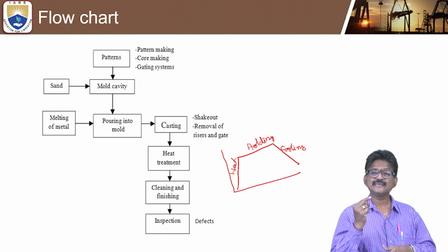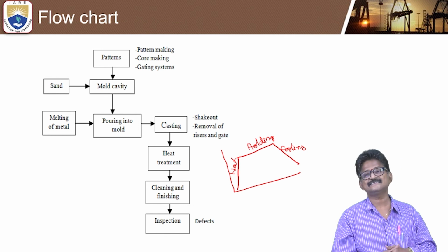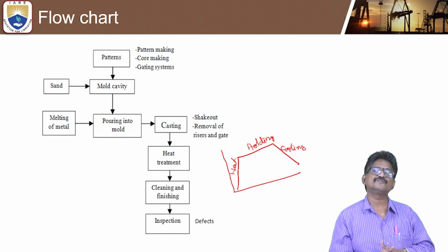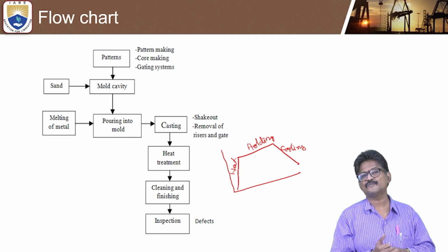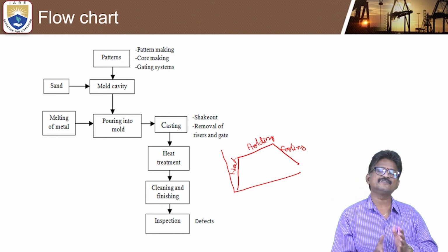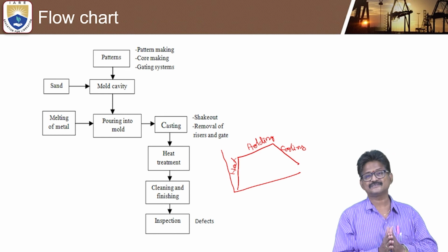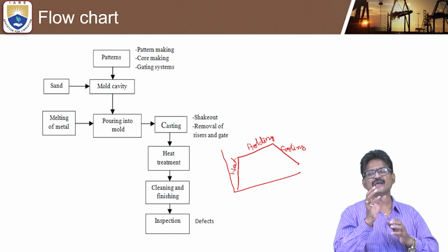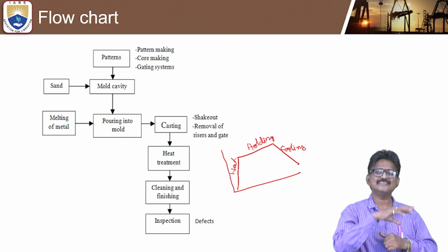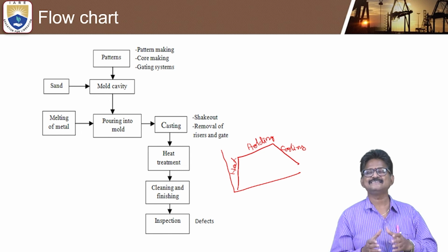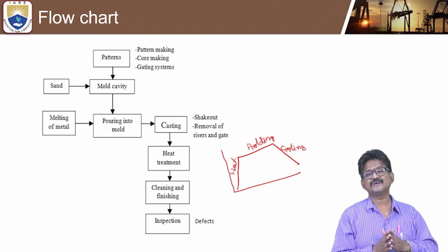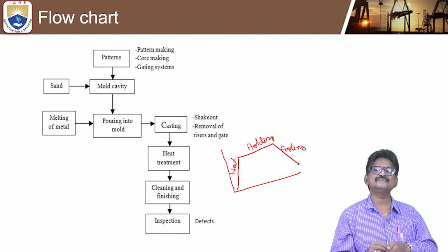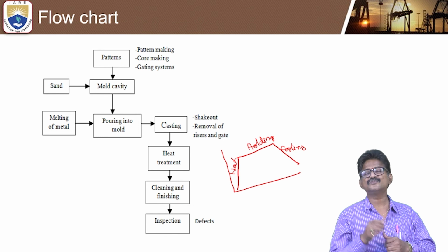Sometimes a single person cannot identify a casting defect, which leads to a lot of difficulties in the final application of the component. That is why inspection is also very important in the sand casting process. Every morning, half an hour to 1 hour is spent with all the sectional top managers, including general managers, to identify casting defects like sand drop, shrinkage, blowholes, and porosity.